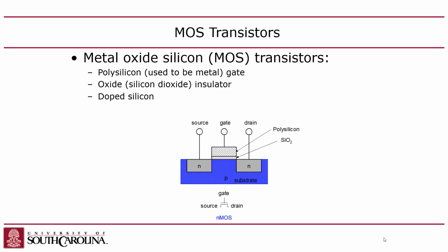There's some electrons in there too, but they're real hard to find. They're very, very rare, very sparse. But if you charge the gate, right, because it's a capacitor, it will attract the minority carriers out of this P-type substrate.